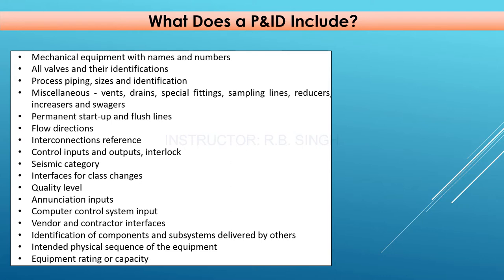either in line, just like flow meters. Flow meters are inline items. So whenever you see the P&ID, there are many flow meters in line. Control valves also will be inline. Some instruments will be mounted online, just like pressure gauges and pressure transmitters. So to do the detail engineering of these instruments, we must know about the piping. We can get those details from the P&ID.